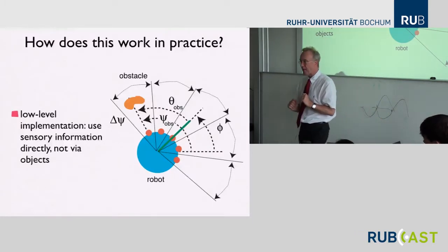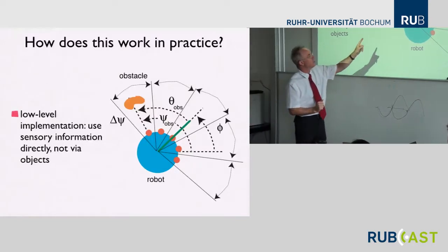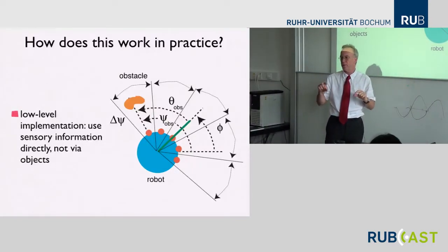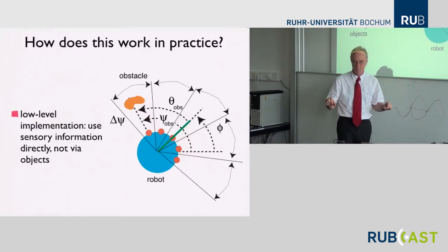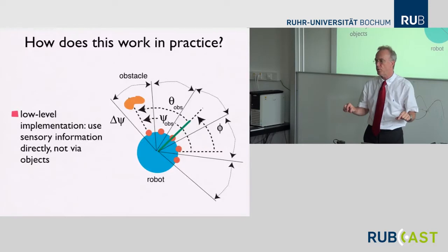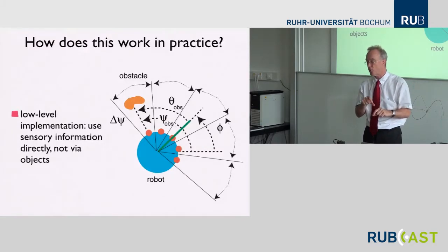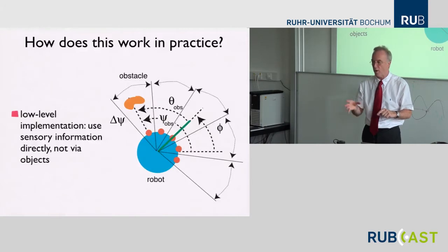And this is what actually happens on this robot. We have these 5 sensors on this robot. These were these little knobs that you might have seen. They are actually ultrasound sensors, but we're using only the infrared sensor that's mounted on top. The ultrasound requires more processing. So this is actually a very simple system.